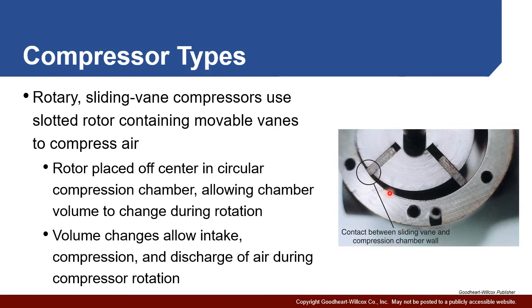As the device rotates, this volume increases, that pulls the fluid in. That's what generates the suction to pull the fluid in, and then as it rotates around, it's going to squeeze back down and push the fluid out. So those volume changes allow you to compress air and move it in a positive displacement way from the inlet to the outlet.